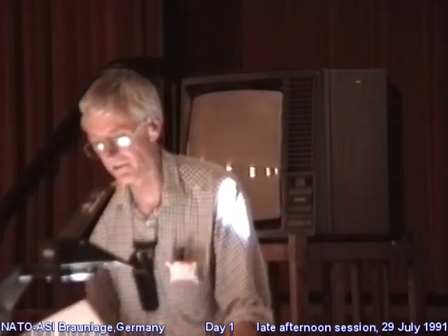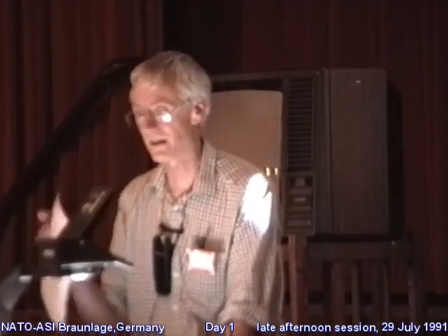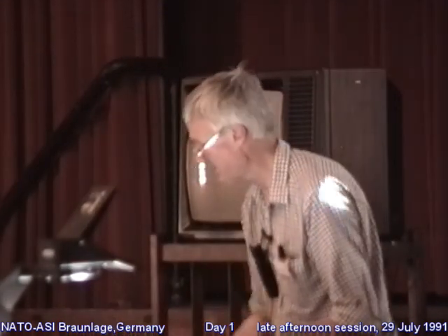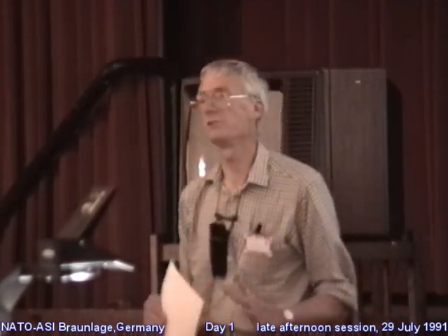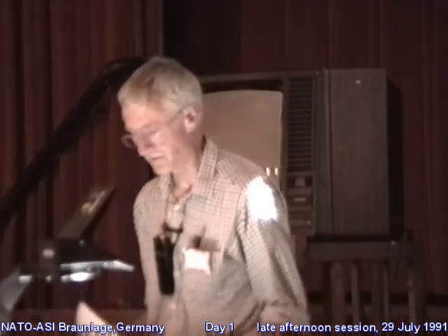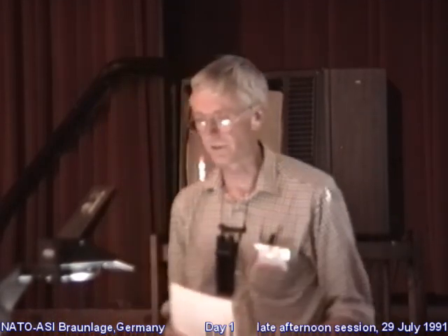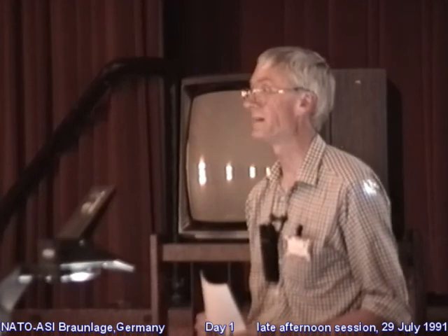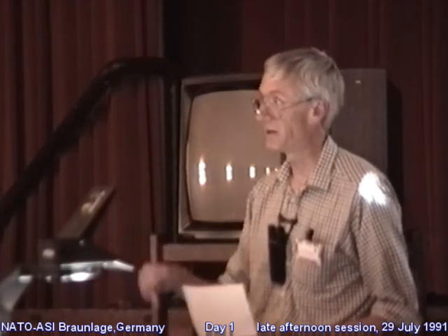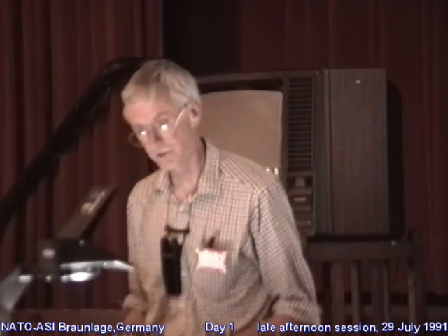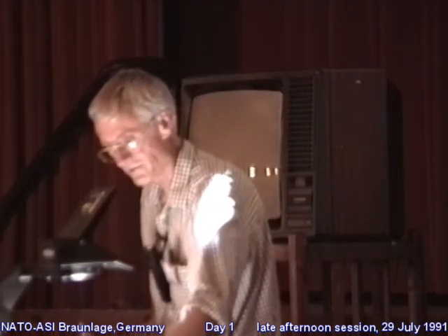I won't go slow enough for you to follow every step because it is all up there on the poster at the back, but this just gives you a taste of what's involved. This is true not only for contact between a sphere and a flat, but for any axisymmetric geometry. It's a two-stage calculation. The first thing you do is find out how delta, which is the distance moved by the external load, downwards in this case, varies with load.